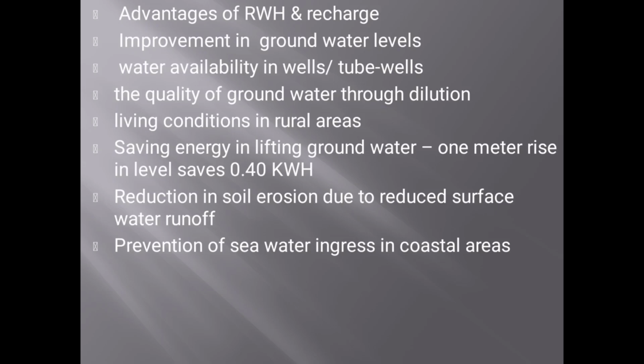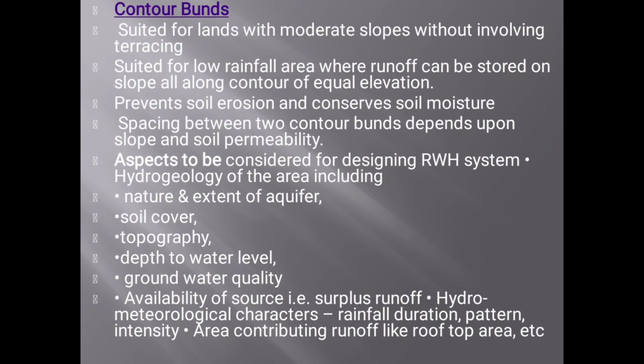What are the advantages of rainwater harvesting and recharge? Improvement in the groundwater table, water availability in wells and tube wells, the quality of groundwater through dilution, living conditions in rural areas, saving energy in lifting groundwater (a 1 meter rise in level saves 0.40 kilowatt hour), reduction in soil erosion due to reduced surface water runoff, and prevention of seawater ingress in coastal areas.